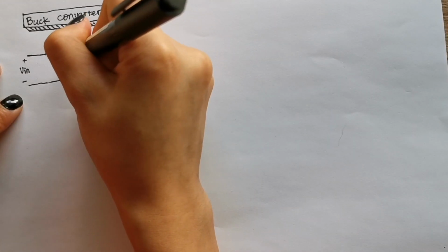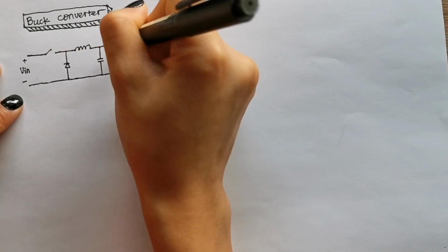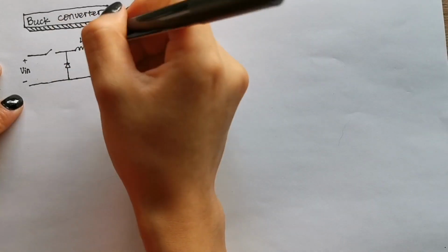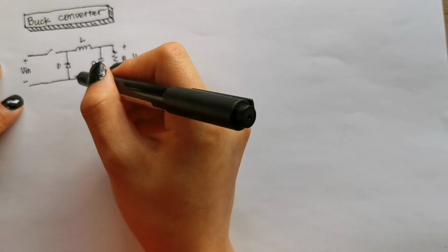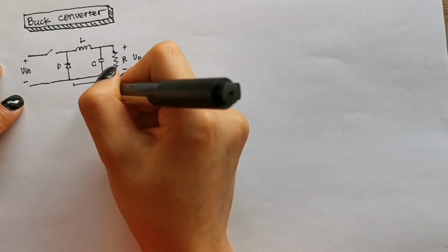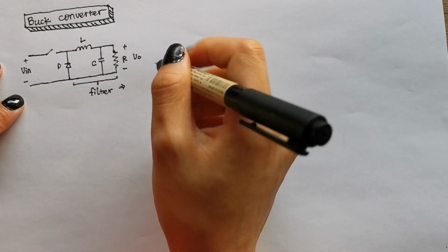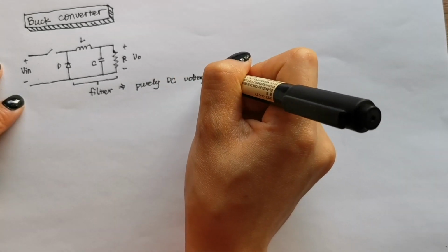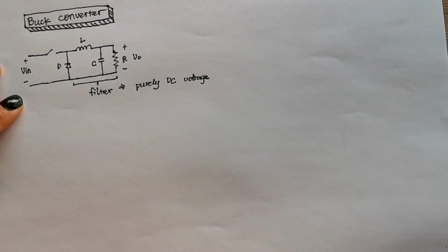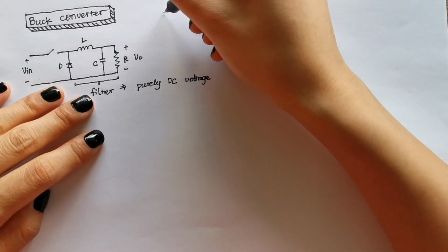Today we will talk about the buck converter. Controlling the DC source using a pulse output voltage is insufficient. We want to produce an output that is more pure. The diode here is used to provide a path for the inductor current. One way of obtaining a DC output is to insert a low-pass filter. This is how the buck converter comes about.